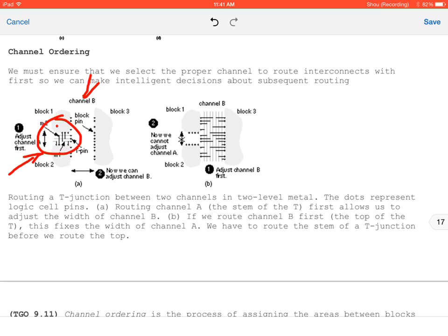If we optimize this huge channel first, we're not going to bring these as close together as possible. You can potentially optimize them at a wide width here, but once you do this, you can't go back and fix that. So basically, you want to optimize the short channel first and then the longer channels. Hopefully that's a short description of a long problem.